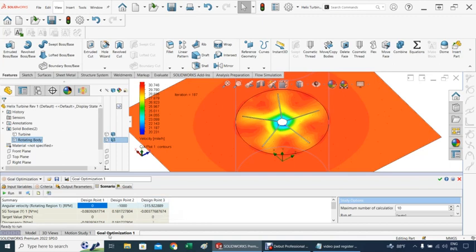If you want to extract energy, the RPM will drop to, obviously, the minimum, which is 0, and this is the maximum torque that you can get. It is around negative. Well, don't worry about the negative. It's just the way that the torque is analyzed here in SolidWorks, but it's about 0.08 newton meter, and obviously that's maximum torque, meaning no energy extraction at all. You have to have something, like a given RPM, to get that. So you need to do another plot in which you plot, for example, watts versus RPM to see where the maximum will happen. Well, more than enough.